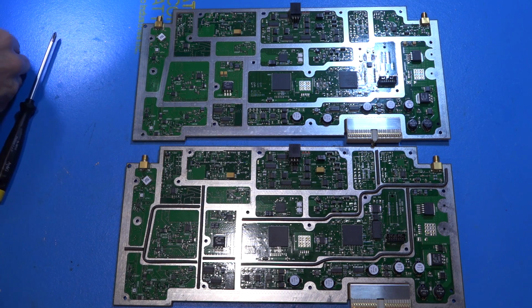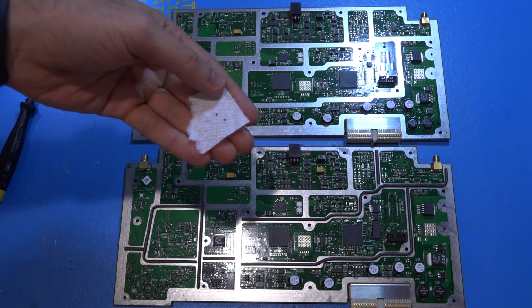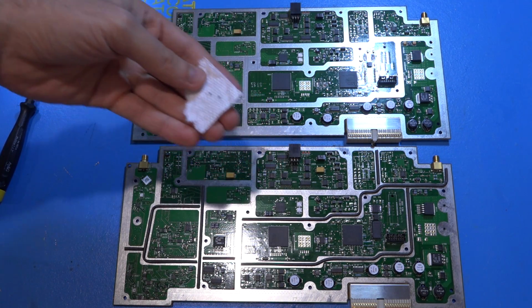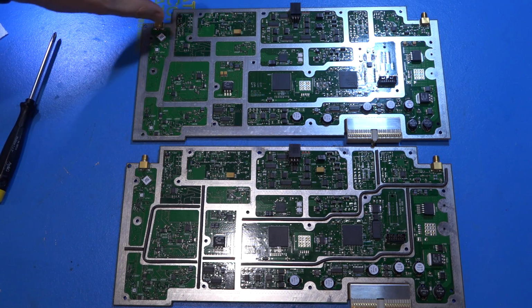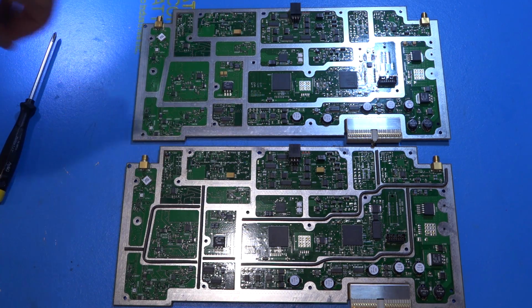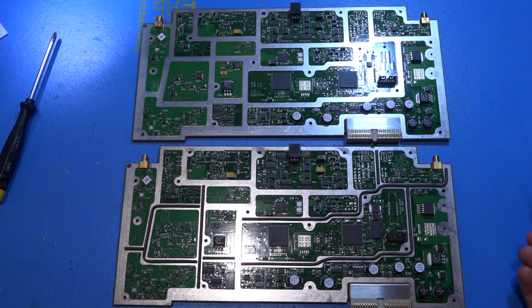And in fact, I have the two diodes, just so you can get an idea of how tiny they are. These are the two diodes that I replaced from this board. So I basically brought some components from here to here. I also replaced one of the op-amps on the other side, which is the buffer of the ADC that does the coarse tuning as well. I replaced that too. So a couple of changes, nothing really major.